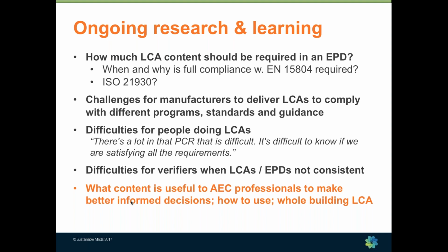We did integrate ISO 21930 into the 2018 version of our technical program, and I'm going to show you a little bit about how we did that. But we always ask when we're working on a PCR, when is full compliance with a European standard going to be required? And when is it not going to be required? Because if it's not required, then all of the LCA tabular results do not need to be in the EPD.